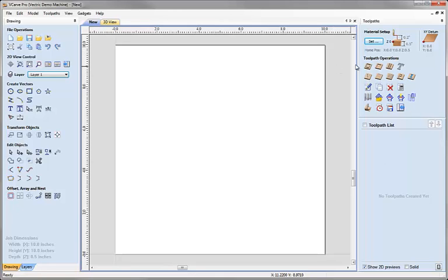Within the icons themselves, the first 2 lines are all the different toolpath strategies that you can access. Things like profiling, pocketing, texturing, V-carving, all the different things that you'll see demonstrated in the tutorials. The third line is administrative options, so things like editing, copying, deleting and recalculating toolpaths. The fourth line allows you to access the tool database, which is where we store all the information, speeds and feeds and the parameters that we want to use for the set of tools that we have, as well as things to do with what we call toolpath templates and tiling.